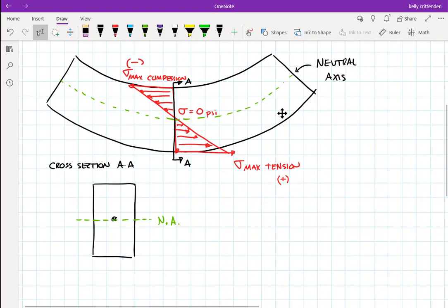Mainly right now we're just going to talk about the beam bending and everything, and not so much the amount of stress that's going on. But anyway, this neutral axis is an important thing. And this is very different from a two-force member, where the whole thing is either tensile, so it's stretching, or the whole thing is compressive, it's compressing, getting shorter.